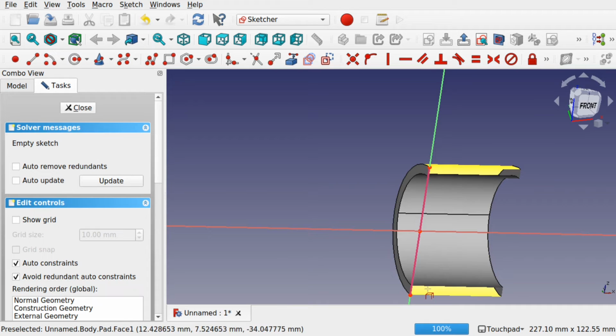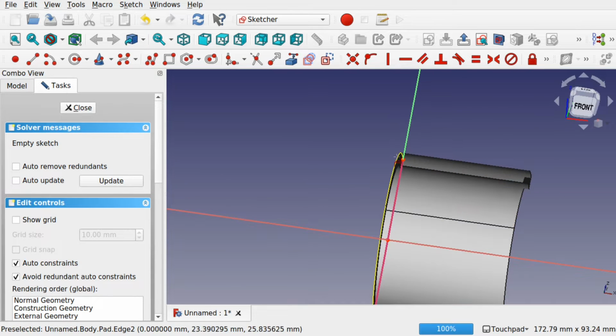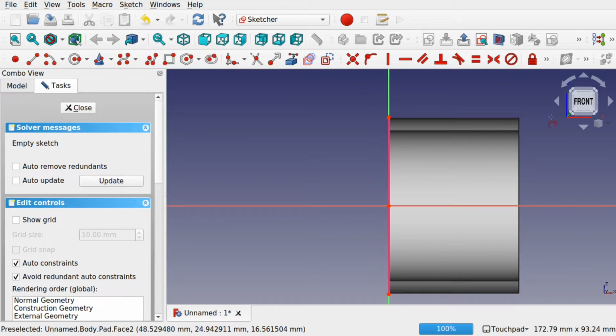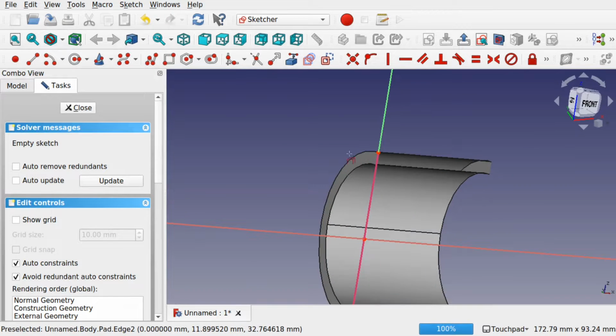So you can see that line is coming. So we can actually attach geometry onto here. We're going to use this for the revolve that goes around here. So a revolve is a profile basically of a circular shape. We're looking at the cross section of that circular shape, and what will happen, it will be revolved around here. So if I put a line in here or a rectangle, you'll get a rectangular lip that goes all the way around here.